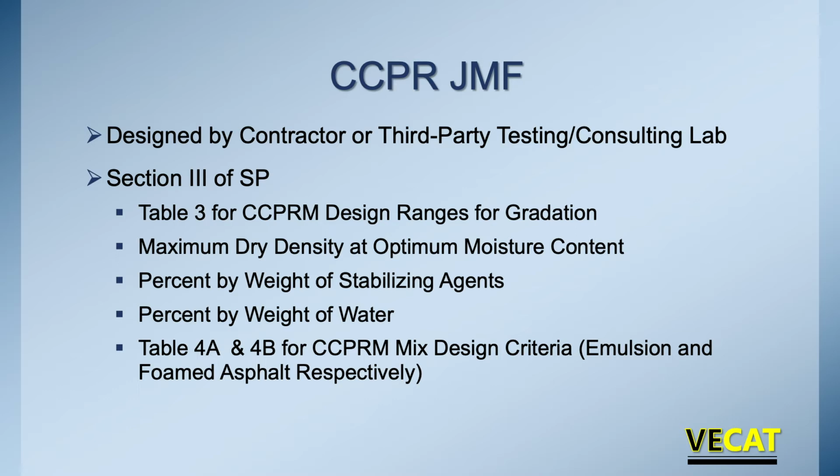What's a little bit different with CCPR than something like asphalt materials is at the moment there is not a CCPR credential for mix design. So as such, it is completely the responsibility of the contractor to have a qualified individual putting together the mix design to meet the requirements in the specification. And as we look in Section 3 of the special provision, we see the details of that job mix formula. In Table 3, it outlines the gradation ranges that the material must meet.